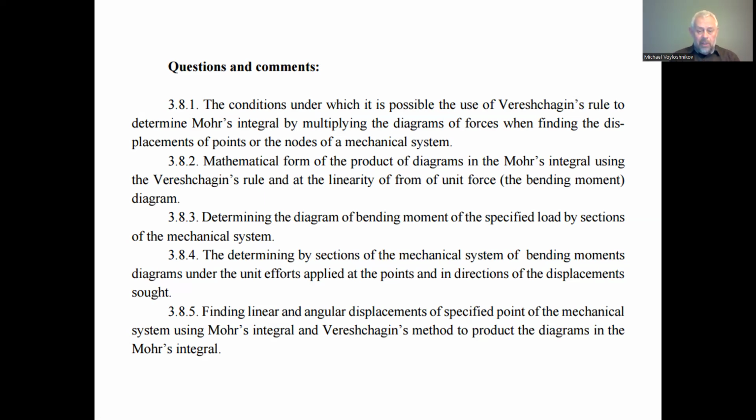That is the mathematical form of the product of diagrams in the Mohr integral using the Vereshchagin rule.